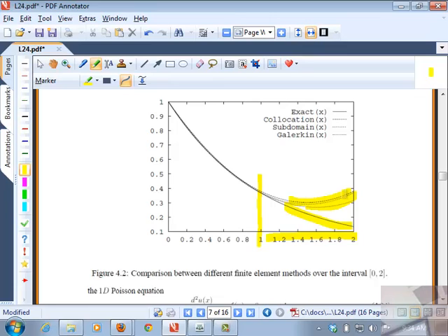Now we have a choice there. You can say, I'm going to use still only 2 degrees of freedom, and that means you're trying to get this to as good a possible solution with only 2 degrees of freedom. It's going to be a bit more challenging. So the error that you will sustain will be higher. But if you increase your degrees of freedom to 3 or 4, chances are that you will get much closer agreement. Why is that? Because the analytical solution is an infinite series. The more terms you take in that, the better accuracy that you get. So you need to mimic that in the same way.